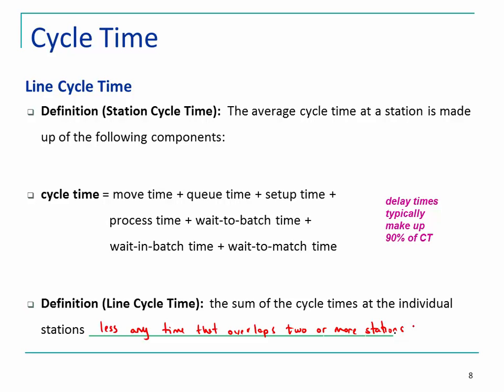In order to compute that cycle time, you need to take into account that there will be some overlapping between the processes, especially if you're doing multiple parts. Maybe when you're processing part 5 on the first machine, you're already doing part 2 on the second machine, and part 1 on the third machine.